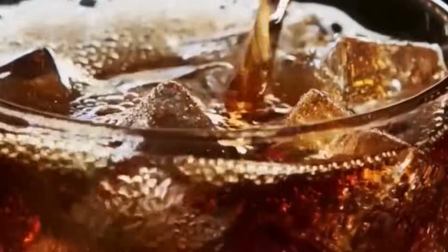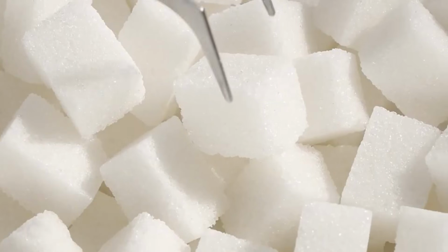Finally, the water passes through reverse osmosis membranes operating at high pressure, forcing the liquid through semi-permeable membranes that eliminate dissolved solids, heavy metals, and microorganisms. The purified water is collected in stainless steel holding tanks, agitated continuously to maintain consistency and prevent stagnation.